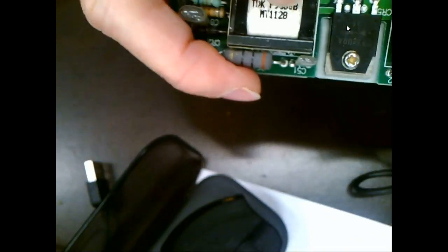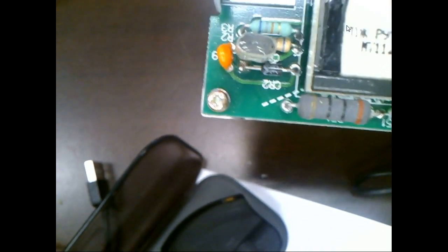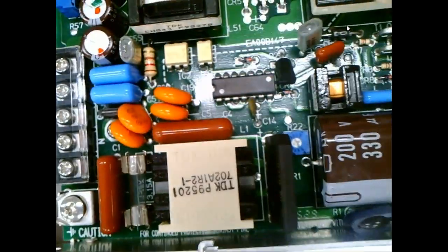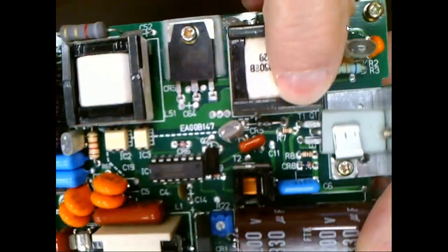If this was an inductor from the outside, inductors are nothing but coils of wire. So your big ones, you're going to actually see them. They're going to look very similar to a transformer. But you can tell them apart because an inductor usually only has 2 leads coming out. A transformer is going to have a minimum of 4, right? 2 for the primary, 2 for the secondary. But I can't get to that because it's mounted and covered up with this shield that's also serving as a heat sink. But I know it's a transformer because it's using the designator what? T, right? What is this guy right here?